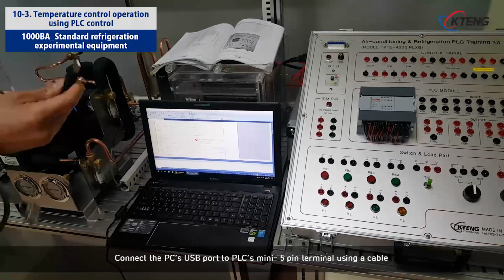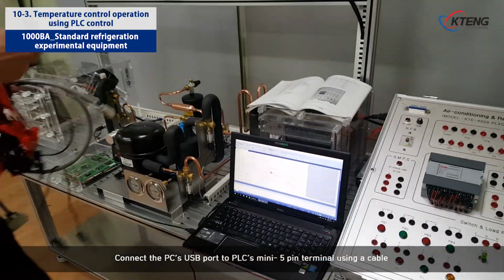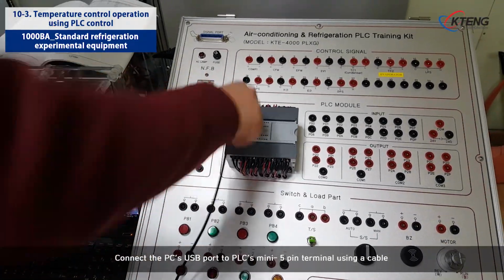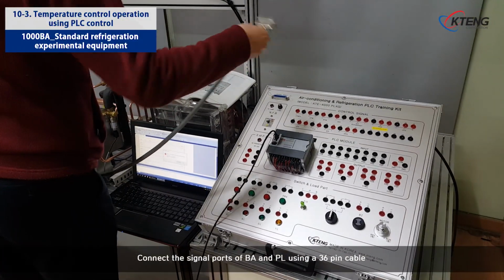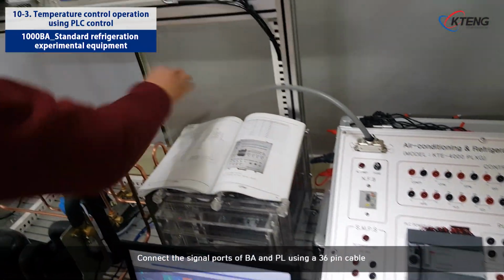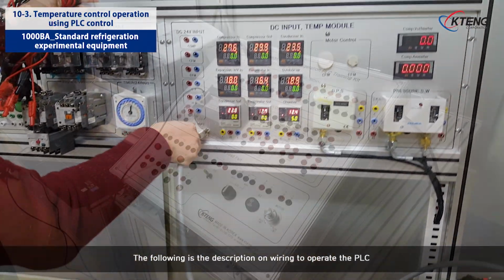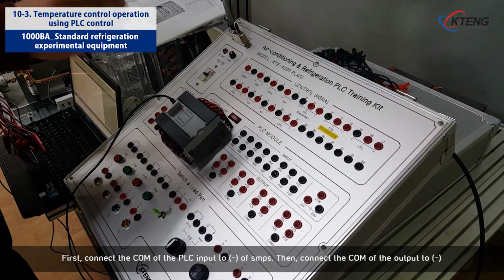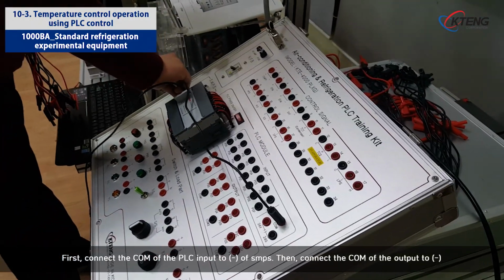Connect the PC's USB port to PLC's mini 5-pin terminal using a cable. Connect the signal ports of the equipment and PLC using a 36-pin cable. The following is the description on wiring to operate the PLC. First, connect the COM of the PLC input to negative SMPS. Then connect the COM of the output to negative.